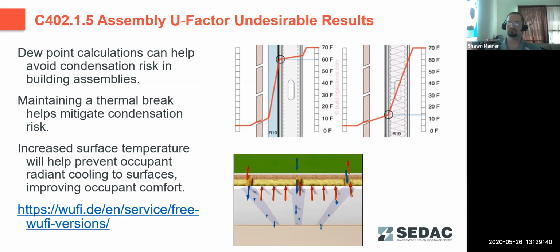you can develop condensation within the wall assembly, and that can lead to degradation of the assembly, mold growth, indoor air quality issues. And for drywalled facilities, drywall with thermal bridging behind it can develop striping in that finished surface on the inside of the building. As condensation forms along those thermal bridges, dirt adheres to it, and you'll get what are called ghost lines. So that's what you're seeing in the bottom image.